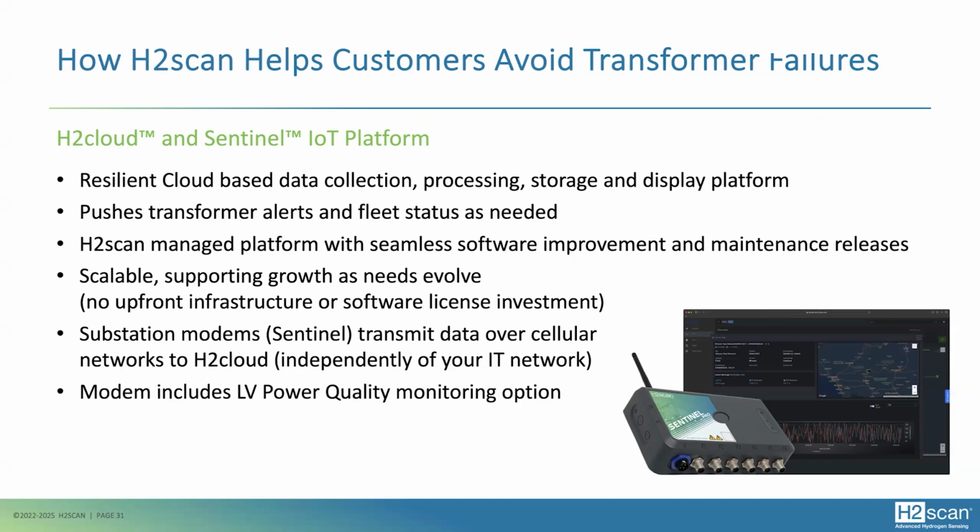It's scalable, so you don't need to buy. You don't need to say, well, when do I need a new machine? When do I need to buy new software? No, it scales with you as you grow. The data is transmitted over the public cellular networks, over private network in the future if necessary, but basically we stay off your IT network, we stay off your OT networks, so we keep everything simple. We don't expose your networks to cybersecurity breaches. And this particular modem also has an LV, so 450 volt power quality monitoring option, so that you can start looking for harmonics too, if you have a connection point.